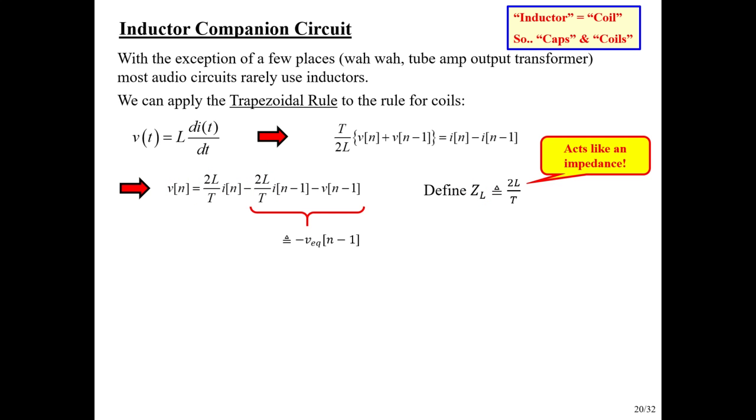And in David Ye's paper, he gets that one right. No typo there. Now I'm going to do a similar thing. Remember, we defined the stuff that was here for the capacitor. We called it IEQ, well, negative IEQ n minus 1. Now we're going to define it to be V, because that's a voltage. Current times an impedance gives a voltage. Same thing that we did before.